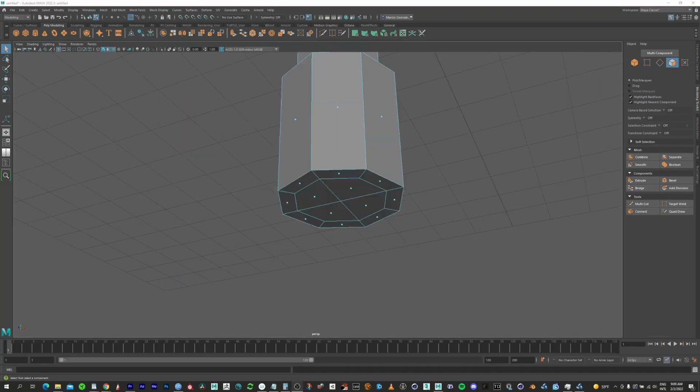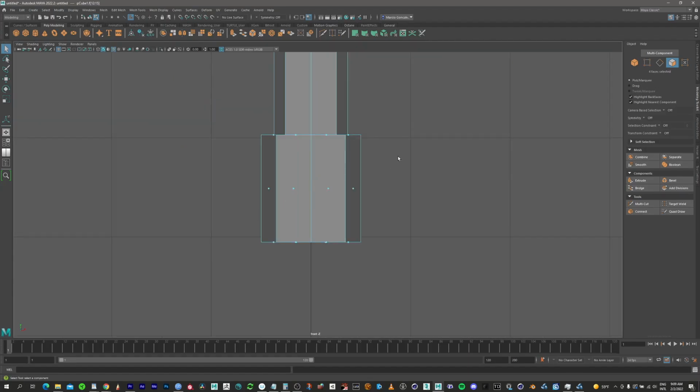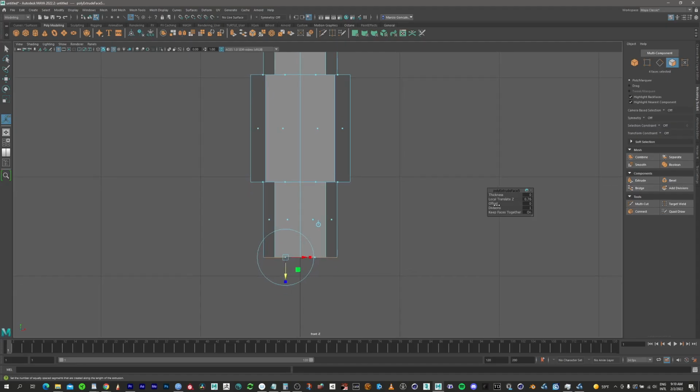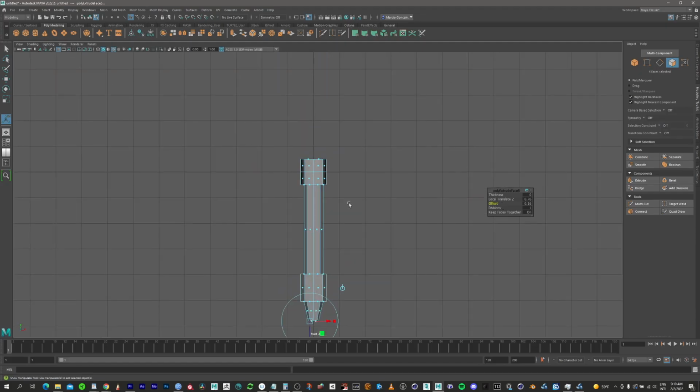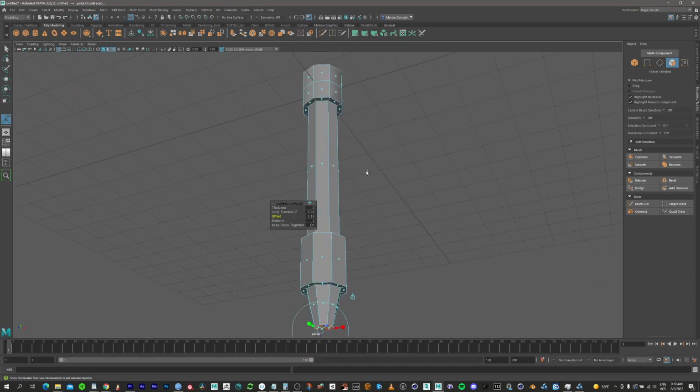Cool. So let's select those faces here in the bottom, and I'm gonna extrude again. In this case, I wanna press the button of the extrude because I'm gonna use the offset. So I'm gonna move here, but I'm gonna move the offset. I'm gonna press Control so I have a more fine-tuned control of the tool. Okay, so far so good. We have the handle of the sword.